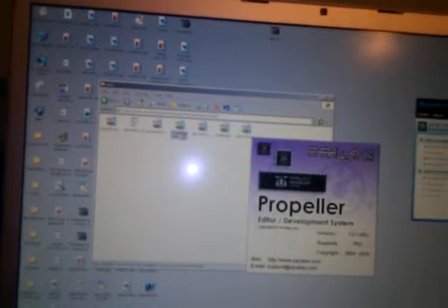You load Propbridge serial. Here we go. Compile it. Know that you're using about half the prop, because this is about half the memory, and you're using 4 cores at the moment, 3 for the USB host and 1 for the main loop.